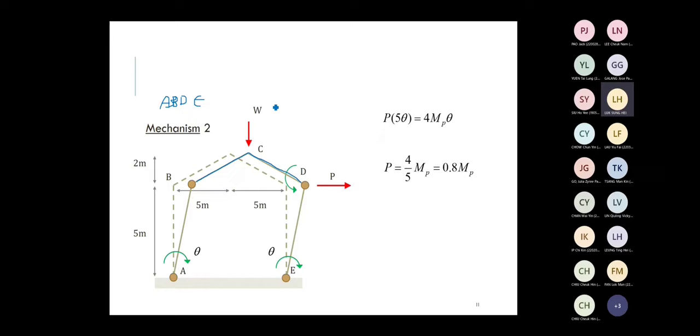That means it remains rigid in our calculations. If this part is rigid, you can replace this rigid part using something like a horizontal member. The upper part BCD is rigid, so to make your calculation easy, you can replace it by a horizontal member. Why am I going to do so?